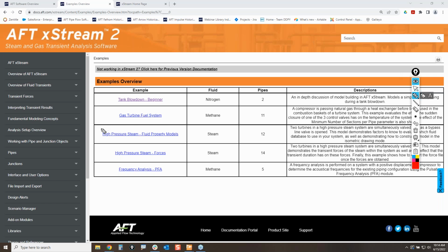And so that's where sensitivity analysis is really helpful. You can follow through this example and this one, and those two examples will look at different thermal property packages and different amounts of sectioning, and you'll be able to get a picture for how much that actually impacts your results.